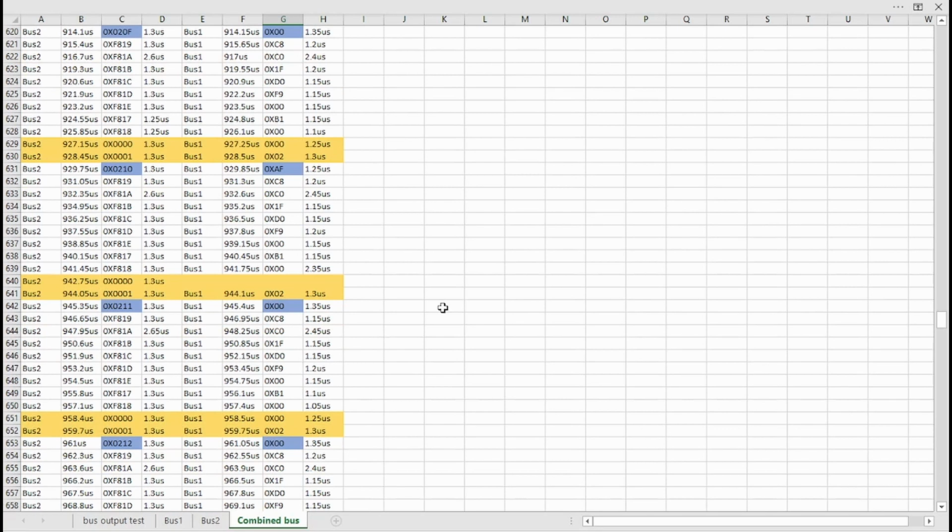We're going to have to be a little bit careful because the Final Tank Battalion game actually has 6 RAM chips and it's got 4 ROM chips. And so as we add those, noise is likely to increase on the circuit. And so we just need to make sure that that's all going to be happy to function together. And the best way to do that is to just incrementally add it and keep checking. So we'll see as we go along with the project that that's all good.